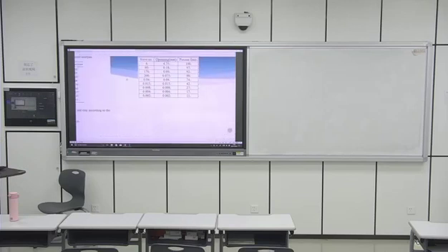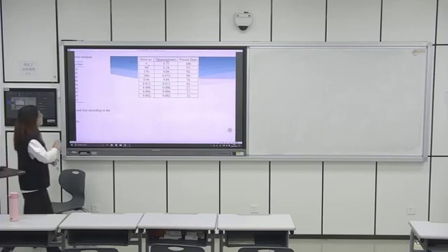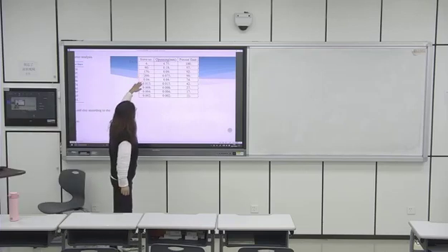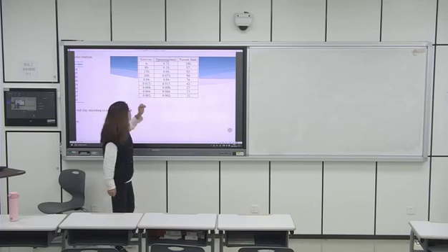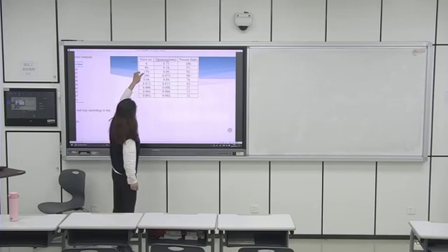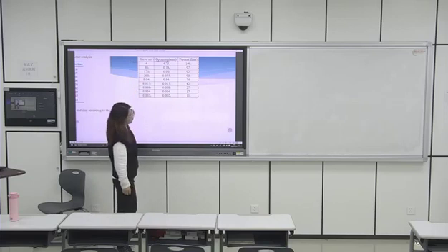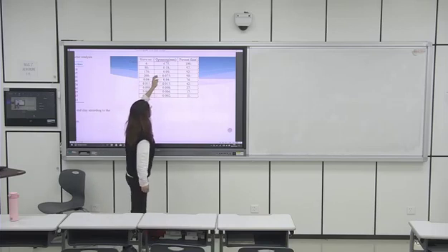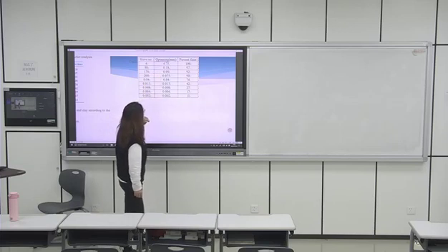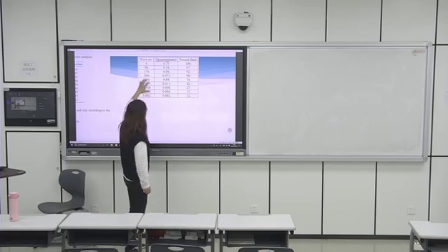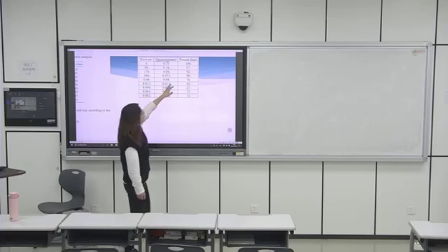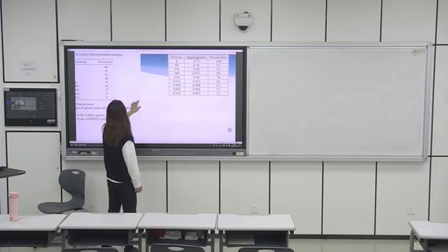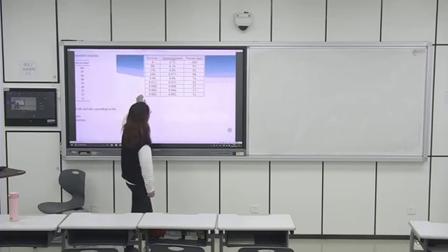First, we know these are sieve numbers, right? Sieve numbers are only for the sieve method. So sieve numbers 4, 40, 100, 200 are for sieve analysis, and each corresponds to an opening size. For the hydrometer analysis, just copy the particle size into the opening column here. And the percent finer is given to you here, so just copy it into the table.